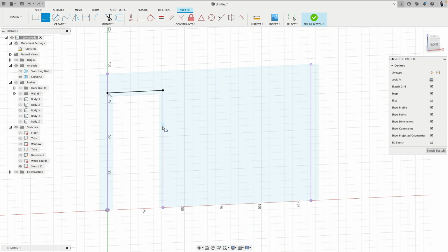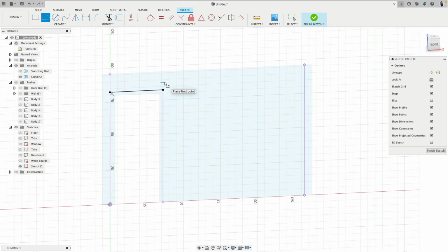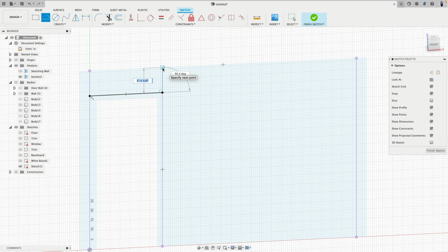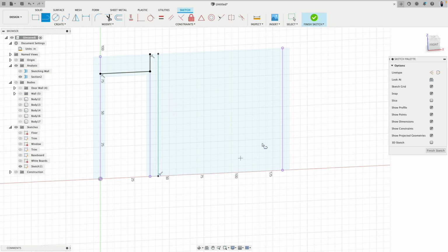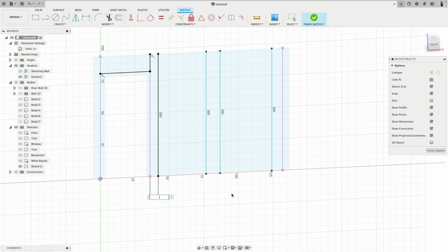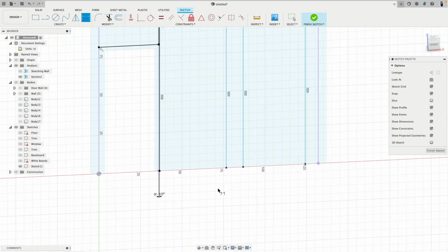Now we have right here, that's actually where the door trim is. So we can have our first vertical board there. And then I create another line. Then here another line. And another line. You see it snaps actually vertically to the height. And then here I have a lot of crazy parallel lines. And these lines are not really very clean. So I remove these constraints and set all this to vertical constraint. Cool. Okay. Then D, make a dimension.